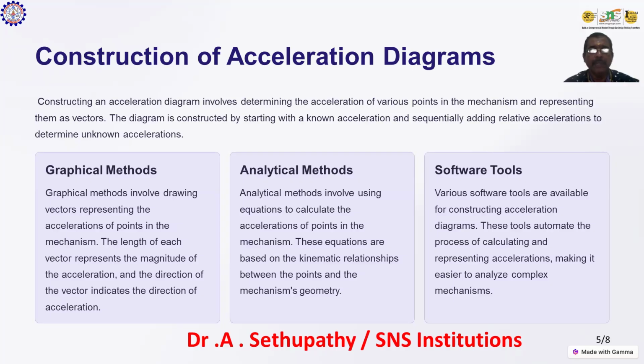The parallel lines are used to convert to tangential acceleration lines, drawn perpendicular to the links used in the mechanism. So the angular acceleration is parallel to the link direction, and the tangential acceleration is perpendicular to the direction of the links at the fixed points.